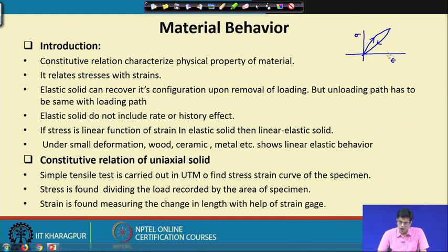So, loading and unloading paths have to be the same, and this implies that there is no change in the energy, because we know from our strength of materials or solid mechanics concepts that the area under the stress strain curve is the strain energy, right. We will discuss this also in detail.